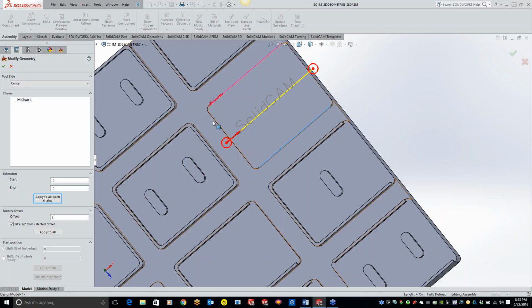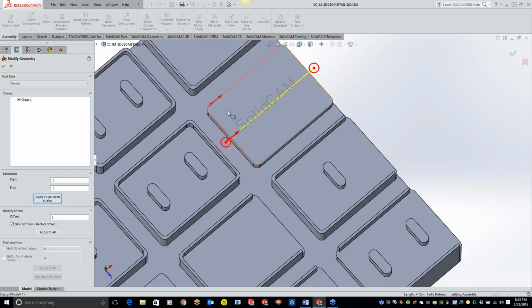So now our end mill is not coming down on the material, it's coming on the outside. And actually, if we just do 0.6, it'll be a little bit better. So you get a little bit of wiggle space there. Now you can also add extensions in the link section of your geometry too. So definitely you can pick and choose where you want to go.